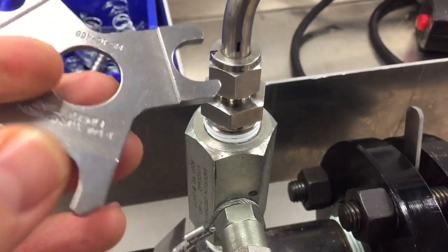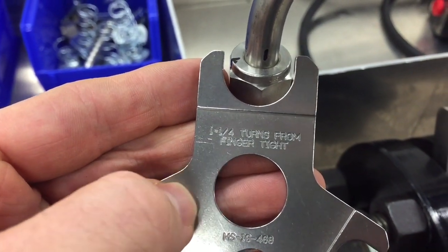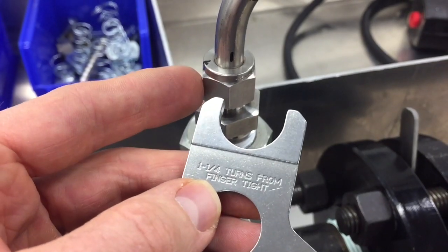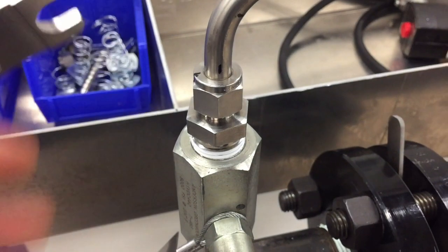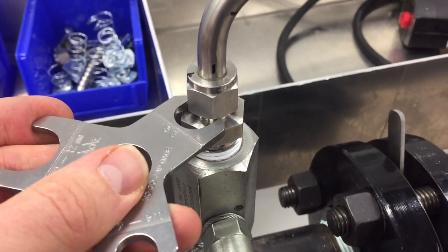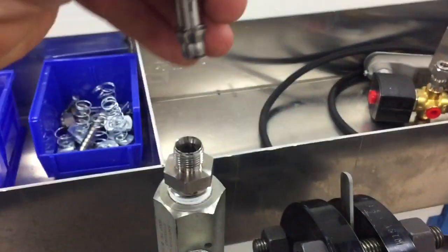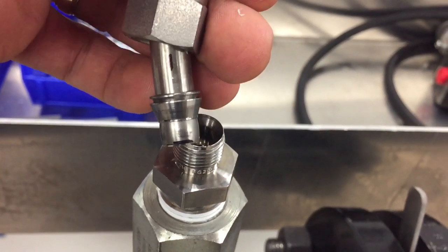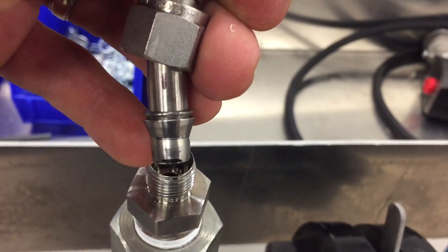One other thing that's kind of neat to see on the back here, they've got it stamped right on here, 1 1/4 turns from finger tight, just to remind the user how many turns we need to make on this fitting for it to seal properly, and for the no-go gap gauge to indicate that it's been tightened properly. So I loosened this nut off with the wrench and pulled this off now, just to show you that's what the nut and ferrule look like compressed down onto the tubing, and you can see the tubing is slightly bulged there as well.